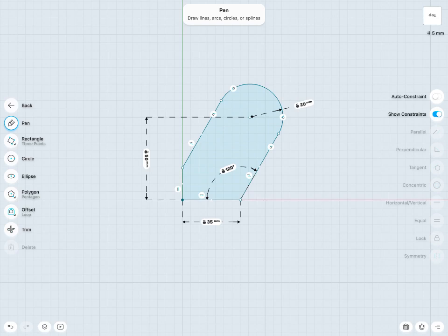So now, it looks like I've fully defined this sketch with a number of constraints and dimensions. So this means that every portion of the sketch has been fully constrained, fully defined, and fully dimensioned. So if I was to try to make any edits by, let's just say, tapping to select any point or line, and if I try to make any changes to it now, notice that it's not changing as it's been fully defined. Of course, if I'd like to make changes or edits, I can just delete some of these constraints or redo and edit any dimensions or constraints as needed.